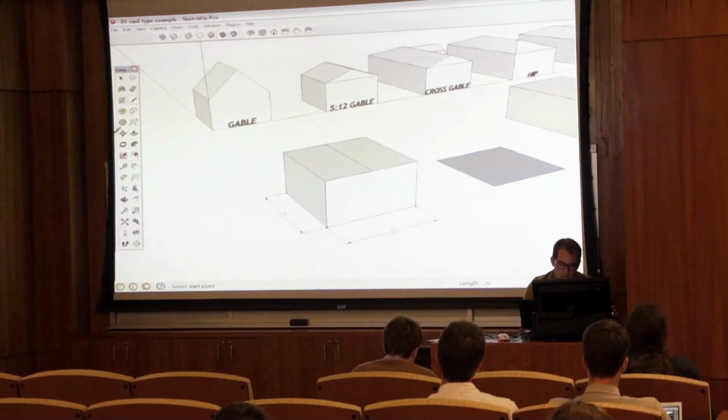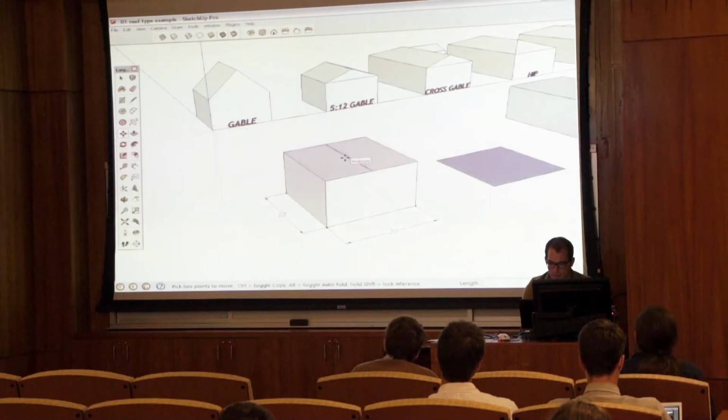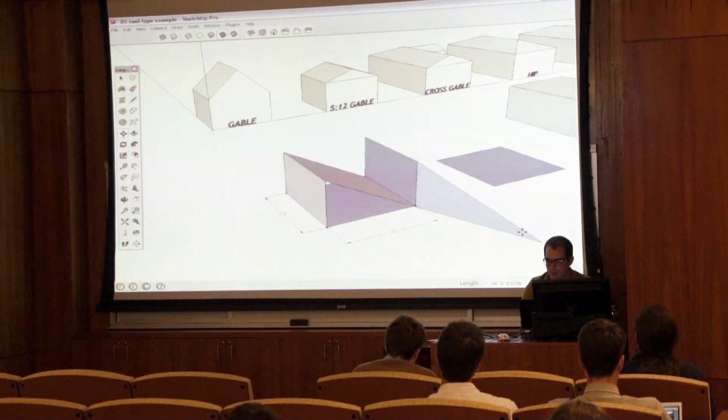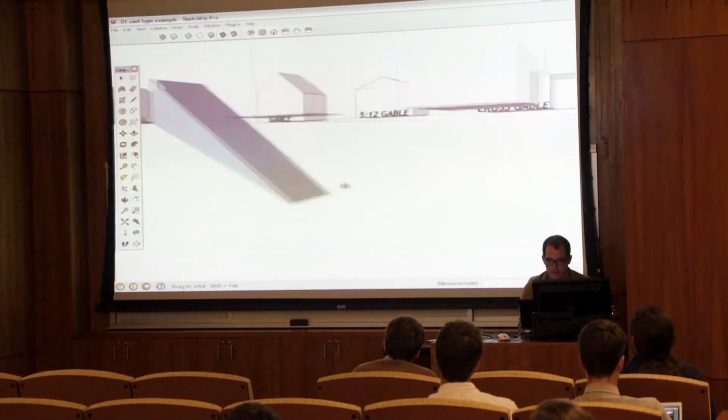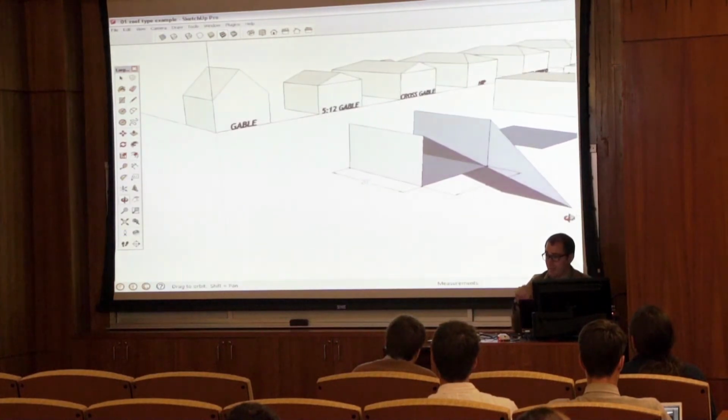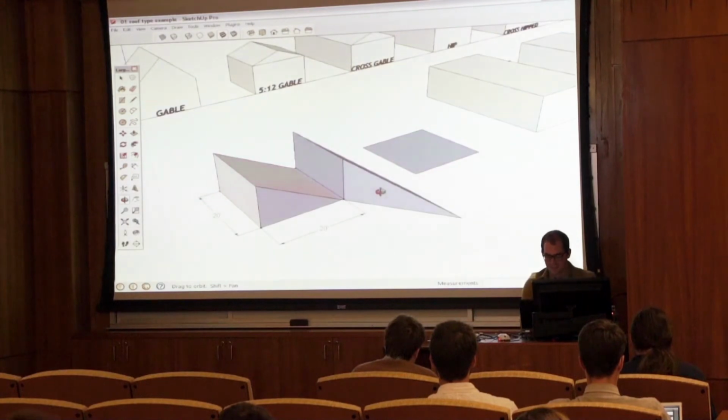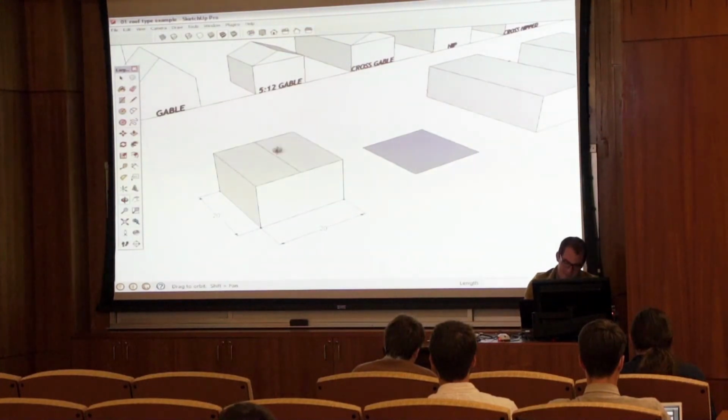Then take the move tool, which is M as a keyboard shortcut, and move this line. You'll see it highlight blue. Move this line up and make sure that you're in the blue axis. If you're not in the blue axis, you're going to get something funky like this. We don't want this. It does happen. Okay. Don't get frustrated. Just undo. Try again.